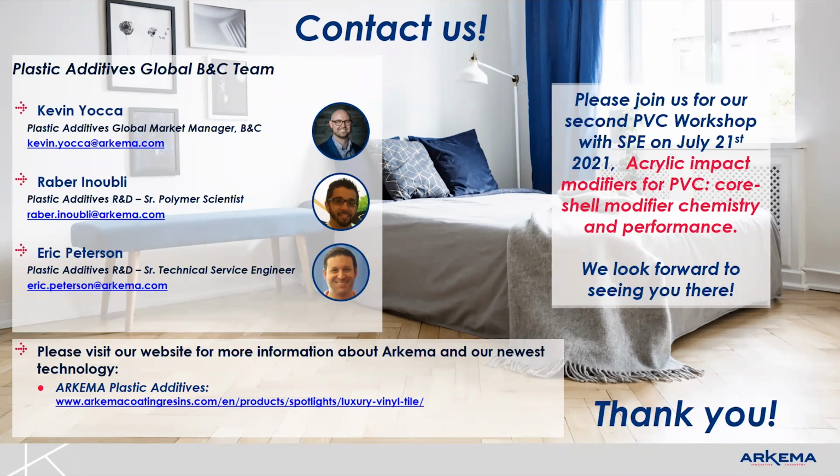Okay, next question. At a high level, can you go over the mechanism of gelation and fusion for a flexible PVC with plasticizer? Yeah, so this is one that I think in one of the SBE final texts, somebody did a really nice job of, and I probably should have included something around it. Basically, the plasticizer coming in helps to swell the PVC, and so the breakdown is essentially easier because you've already started that process a little bit.